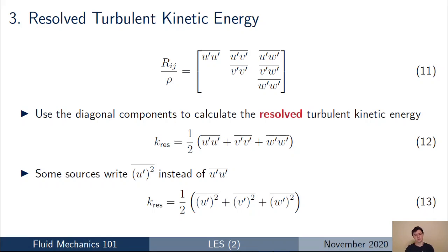The reason that we add the diagonal components together is that, if we think of a flow field, we may have some turbulent kinetic energy in the x direction, some in the y direction, and some in the z direction, but we're concerned with the turbulent kinetic energy at the point, which is a scalar value, and so we want the sum of that energy in each of the different directions added together. That's why you'll see the turbulent kinetic energy as the sum of uu, vv, and ww.